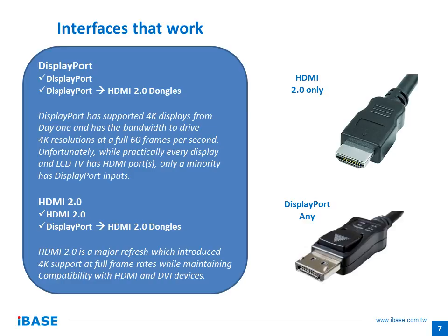It almost doesn't exist. Which means that you may or may not have DisplayPort available to you, but you will always have HDMI available to you. With HDMI, though, you want to be sure that it's HDMI 2.0, and it has to be HDMI 2.0 for the display, HDMI 2.0 for the player. Both have to be HDMI 2.0 compliant. Then and only then can you drive 4K resolutions at the full refresh rate.